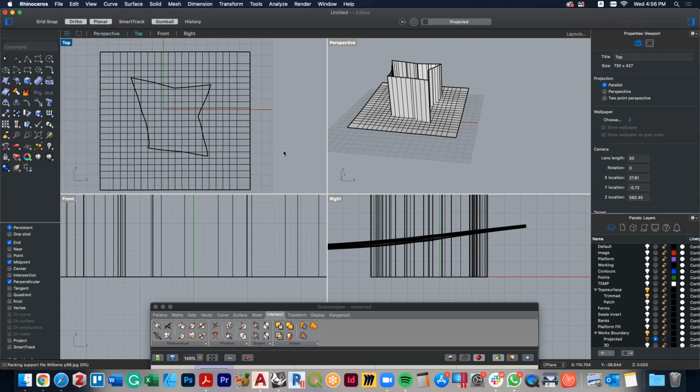So now I'm going to be optimistic. And if this doesn't work, I'm going to pause this, fix it, get it right and come back. So what I'm doing is I'm going to trim. It wants the cutting object. Again, for those of you who've never used AutoCAD, read the prompt. That's the thing, read the prompt. That's what you want to be doing all the time.